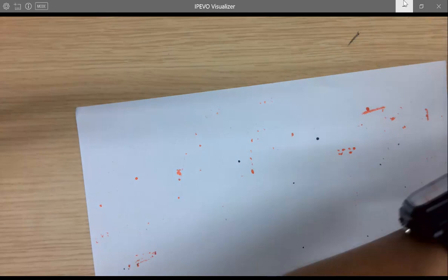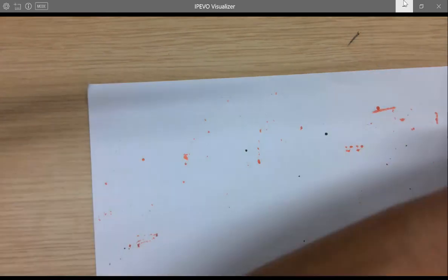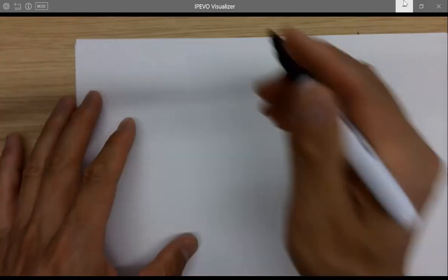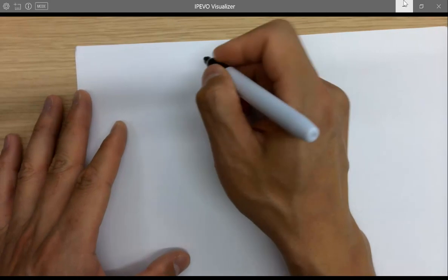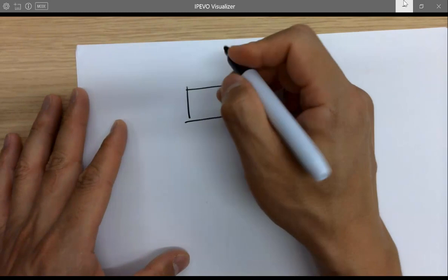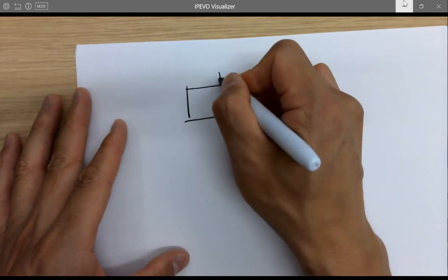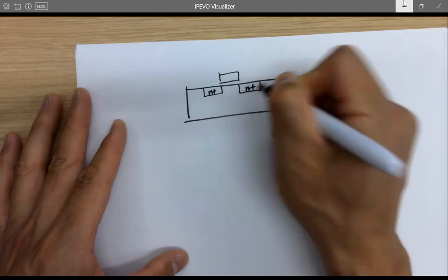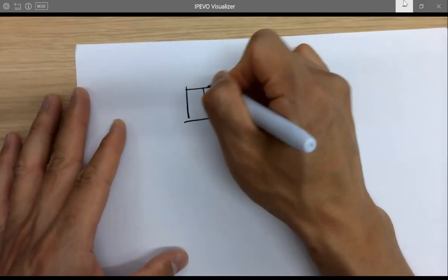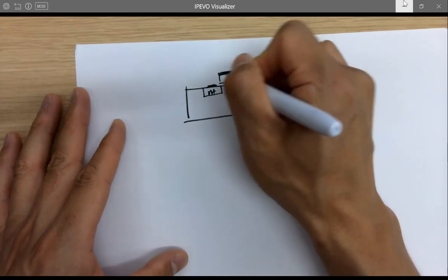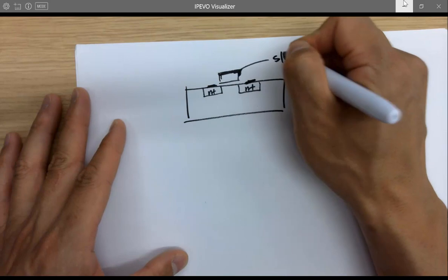And there's a way that you can use the polysilicon layer as a resistor, but with a lower resistance. The way to do that is, here's a gate, for example, and that's N plus. You can reduce the resistance of the contact and also the gate by depositing a layer on it. It's called silicide.